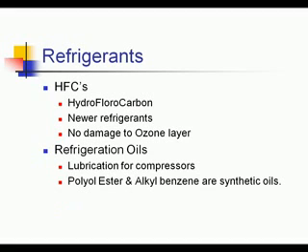There's a couple different refrigerant classifications. For example, CFCs. Okay, they can contain chlorine. They're called chlorofluorocarbons. They're old refrigerants, and at this point they've been phased out. You may still come across them in equipment, but it's very tough to buy new CFCs. HCFCs, hydrochlorofluorocarbons, they're a little bit more environmentally friendly because they've added some hydrogen rather than the chlorine. You'll find that it's R22 and a couple other refrigerants that you'll find in a lot of the residential systems out there. Again, HCFCs are being phased out. You can no longer buy new equipment with HCFCs in them.